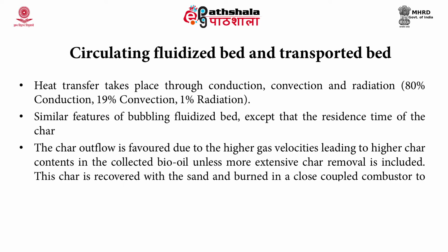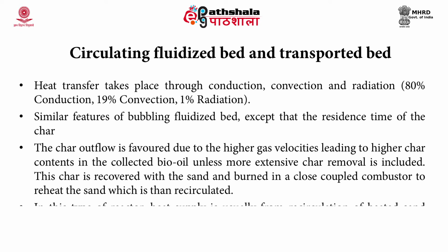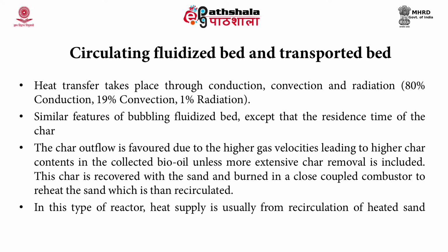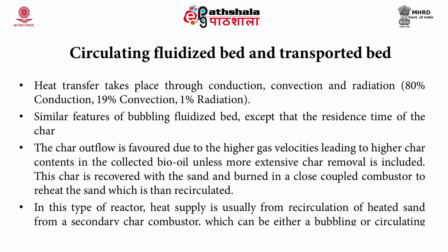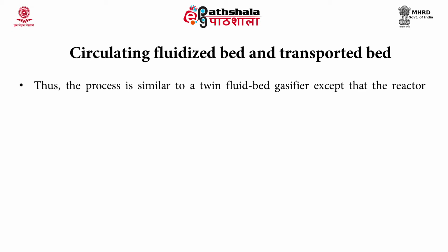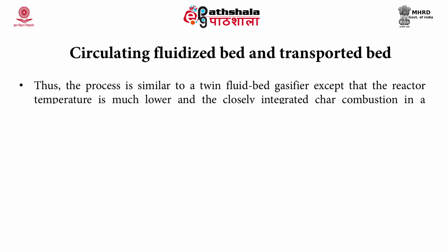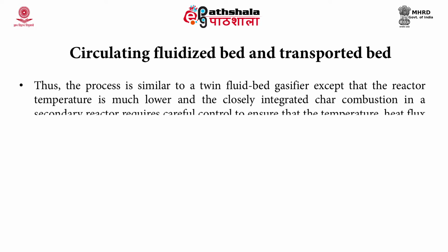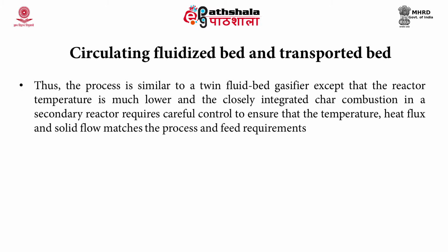This char is recovered with the sand and burnt in a close coupled combustor to reheat the sand, which is then recirculated. In this type, heat supply is usually from recirculation of heated sand from a secondary char combustor, which can be either a bubbling or circulating fluid bed. Thus, the process is similar to a twin fluid bed gasifier, except that the reactor temperature is much lower and closely integrated char combustion occurs in a secondary reactor.